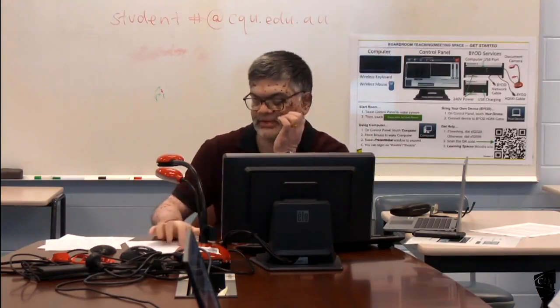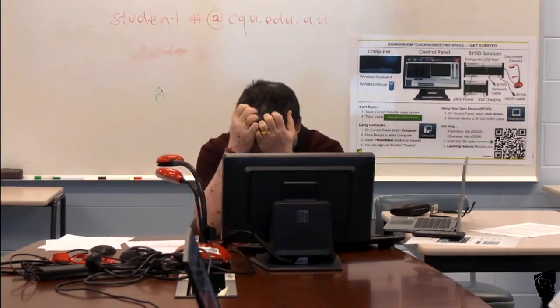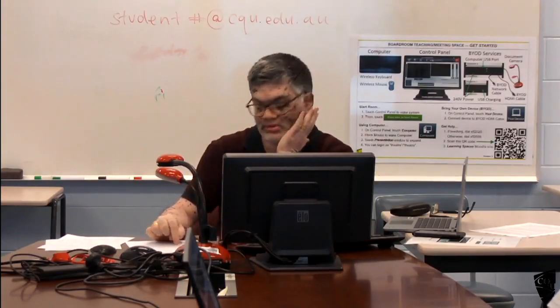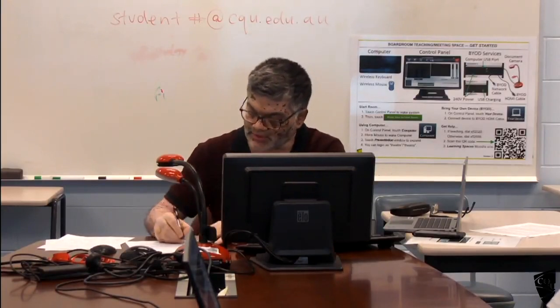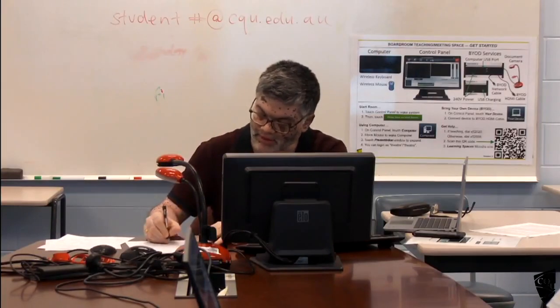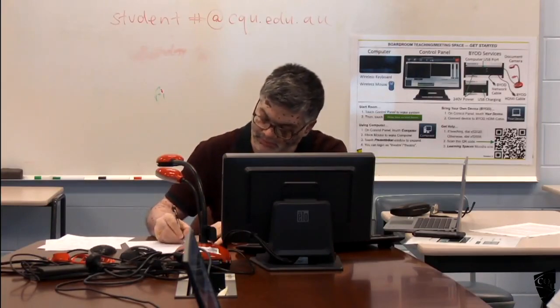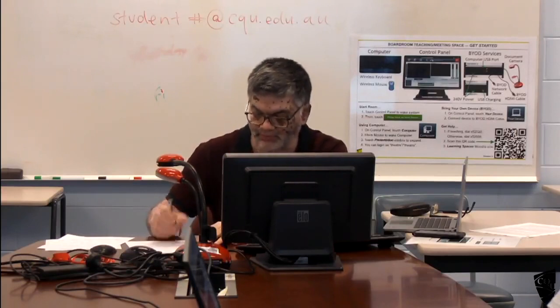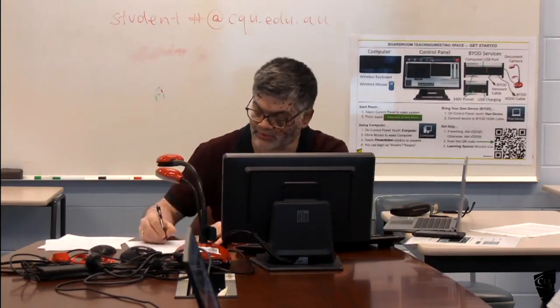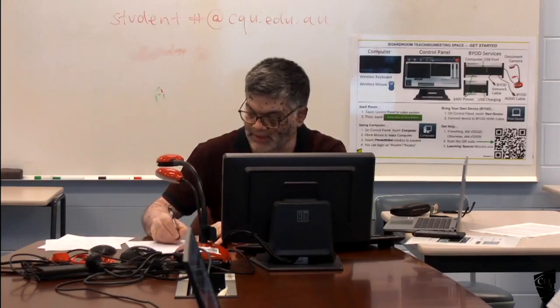So then we will design for this moment. So we know the maximum moment at support, say 600. We know the column strip. Column strip is LT by 2, half of that. And you know the bending moment is, say, maximum is 600.